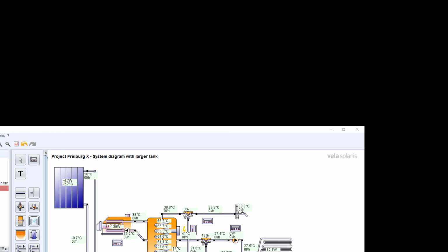The values in the storage tank, where we have 12 layers, and for example here on the 5th of January during noontime, we see our solar loop pump is running. We are gaining energy, roughly 6 kilowatt, and we are going back to the storage tank with a larger temperature than we have run into the collector.